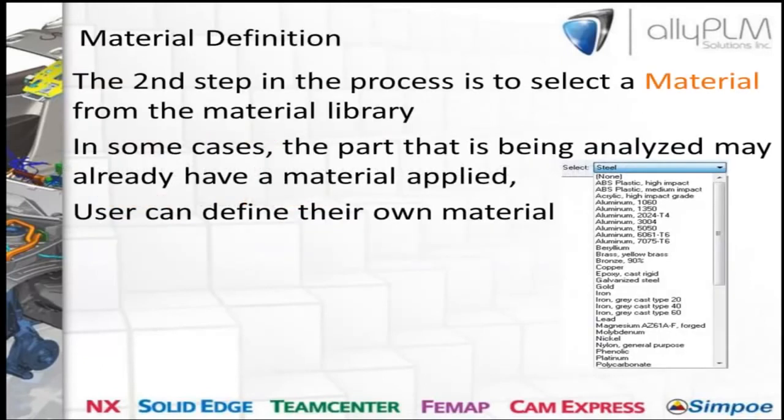And then comes the material definition stage. Here you define what type of material you want to use for that model. If you have defined your material inside Solid Edge, you don't have to define it again. It automatically links to that material. You will have this list here, and you might know we can always add materials; this list comes from your material table inside of Solid Edge.